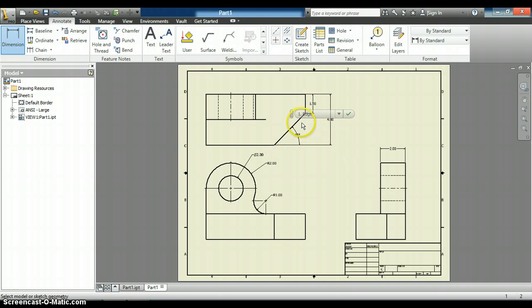Oops, if it goes away. There it goes. Alright, so now we want our dimension from here to here, and we can add that in right there. We could add it in line with this one because in this case we're not measuring all the way across, so we don't have to worry about sticking it out here. So we'll line those two up. Now we have our distance here. We know that this is a 45, so therefore if this is a 45, that means that this distance here should be the same distance as this one right here, which is 2.5.